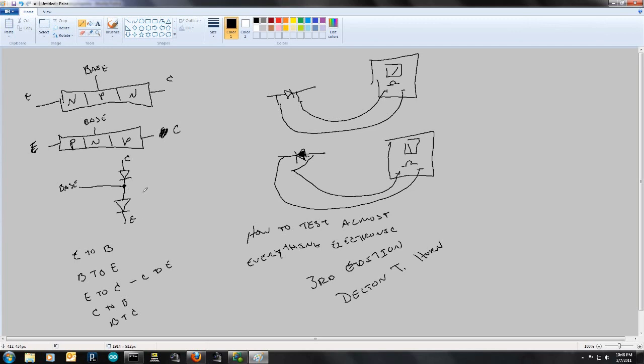So put it in your breadboard and use your leads. Not on your multimeter, but connect your leads to alligator clips, and then from alligator clips to those nice wires that we use on our breadboards. And you can do this testing. Basically, if my PNP or NPN isn't working in my breadboarded circuit, I try another one. And if that's not working, then I look at the way I've built my circuit. I actually have a multimeter that I can stick them into, and it does all this testing for me and tells me whether it's good or bad. And it does it almost instantaneously.